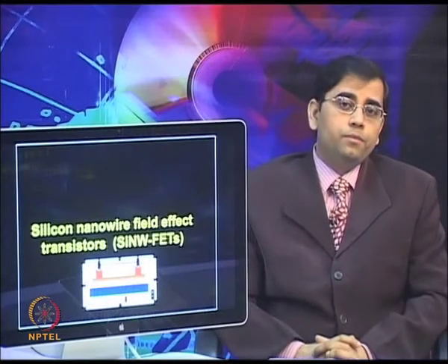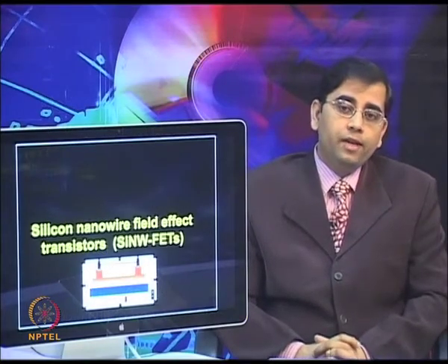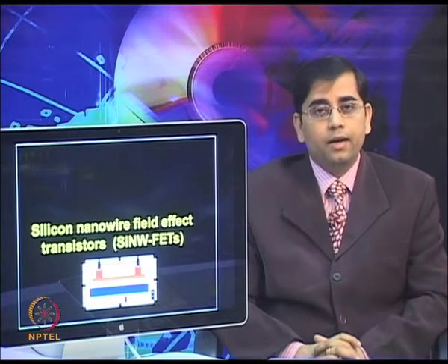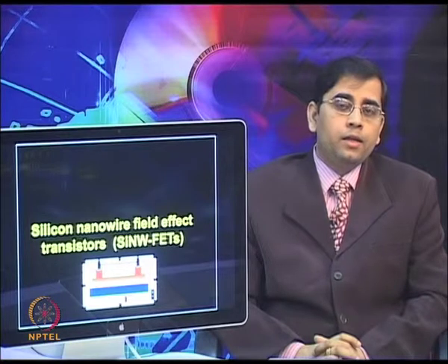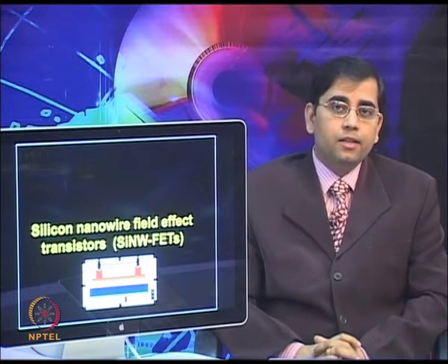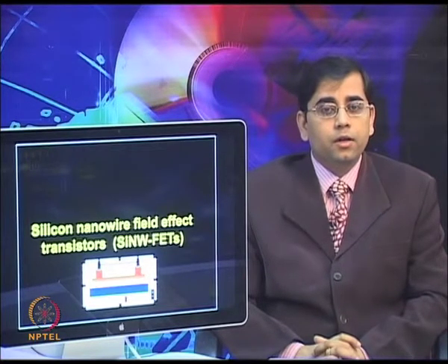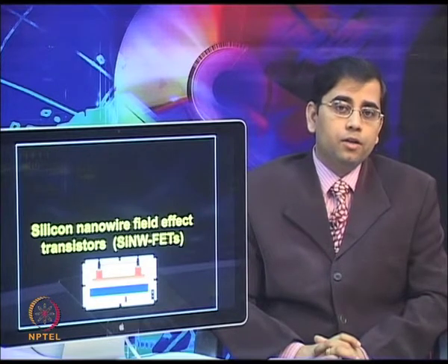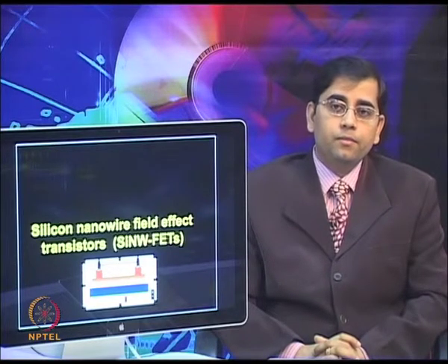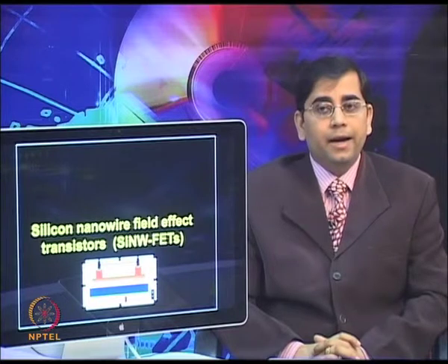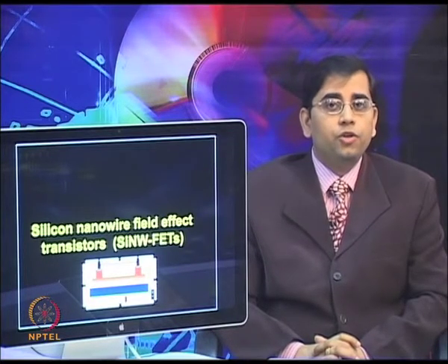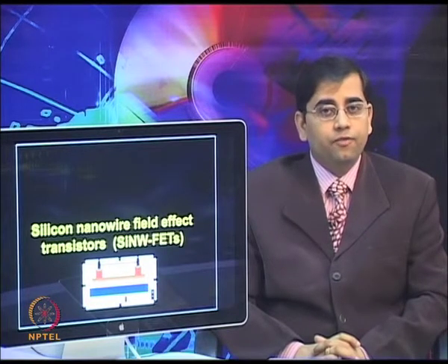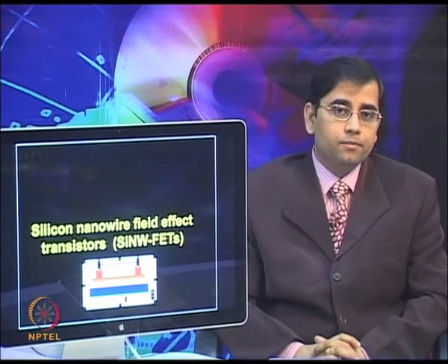Let us now talk about silicon nanowire field effect transistors or SiNW-FETs. The planar field effect transistors modified with molecular receptors for the analyte of interest can monitor the binding of charged species through the accumulation of carriers on the surface of the transistor.